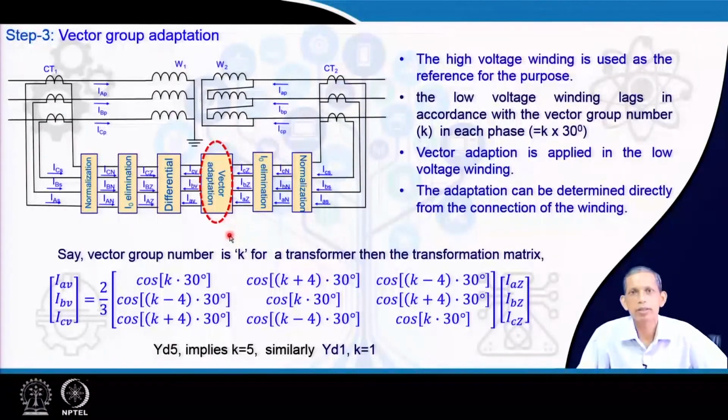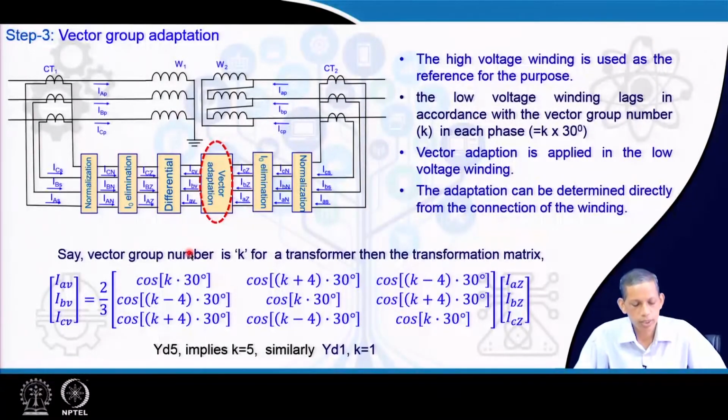And then we also learn that in the case of the negative sequence, it happens to be the reverse, a minus 30 degrees or lagging angle. So, considering the positive sequence and negative sequence perspective, the e to the power j theta and e to the power minus j theta terms come here, and using that, the corresponding matrix comes out in terms of the cos terms which we are getting here.